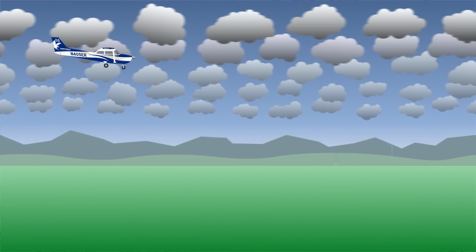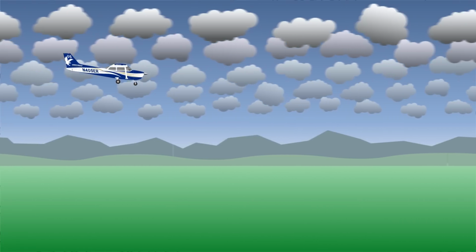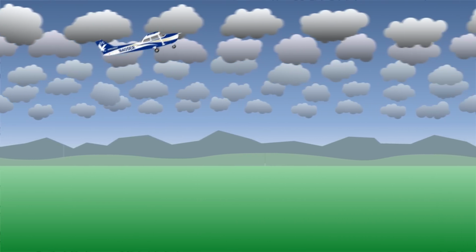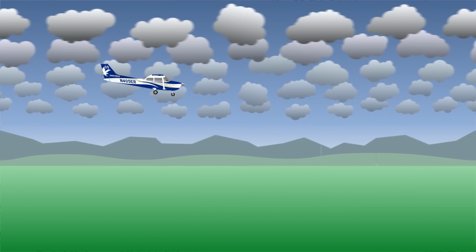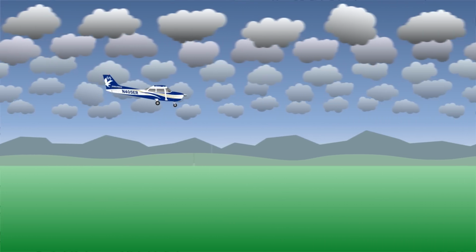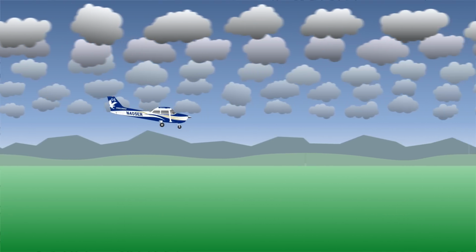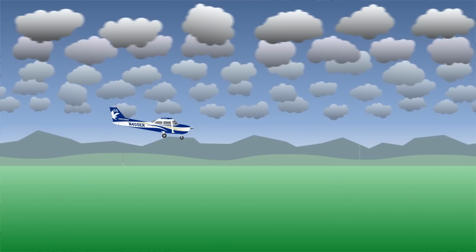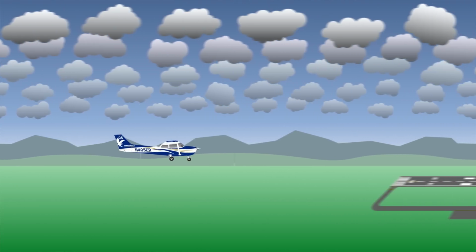311 feet is the decision altitude for this approach, so at that point, if the runway or approach light system is not in sight, you must perform a missed approach. If you meet the requirements to land as specified in 91.175, keep using the localizer and glideslope to continue to the runway. This approach was designed for low visibility, so ensure that you continue to track the navigational aids all the way to the roundout.